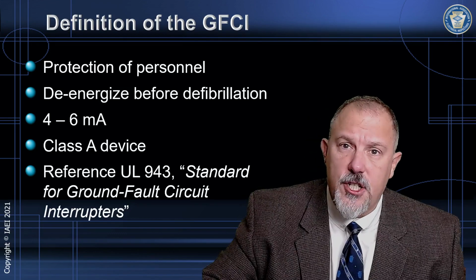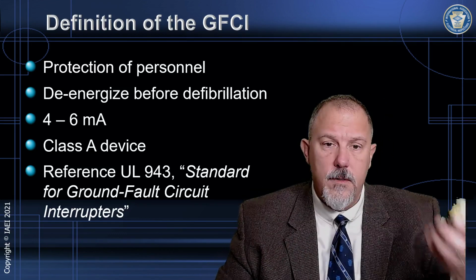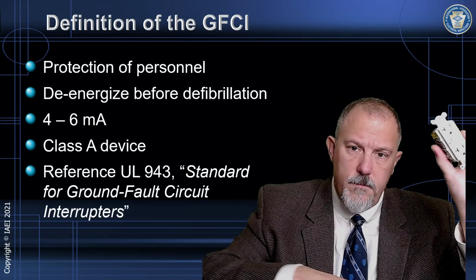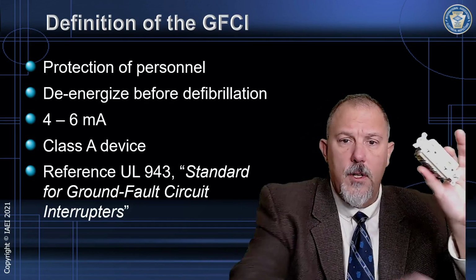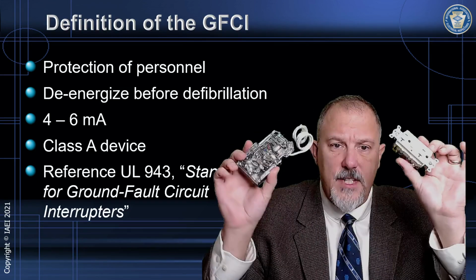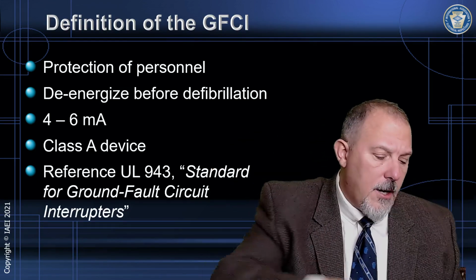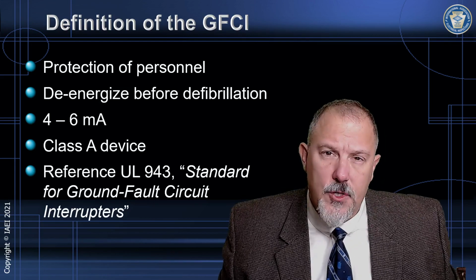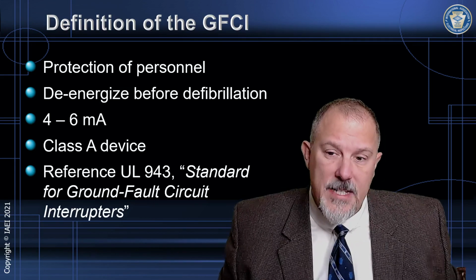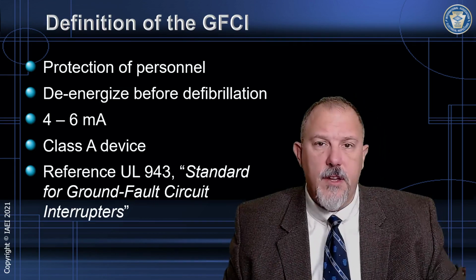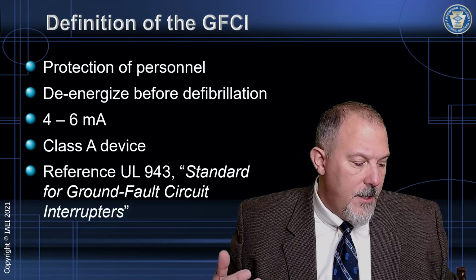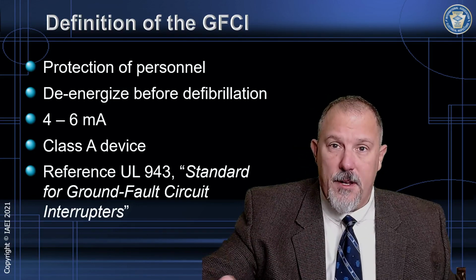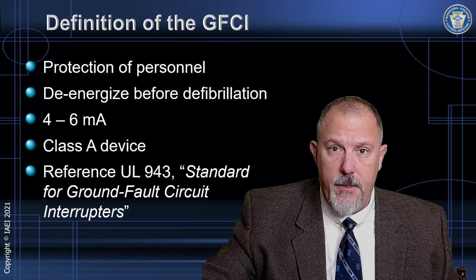This device is a protection of personnel. Whether it be a receptacle type GFCI or a circuit breaker type GFCI, these devices are your last resort. From a safety perspective, we don't think of the GFCI as the primary method of providing protection.